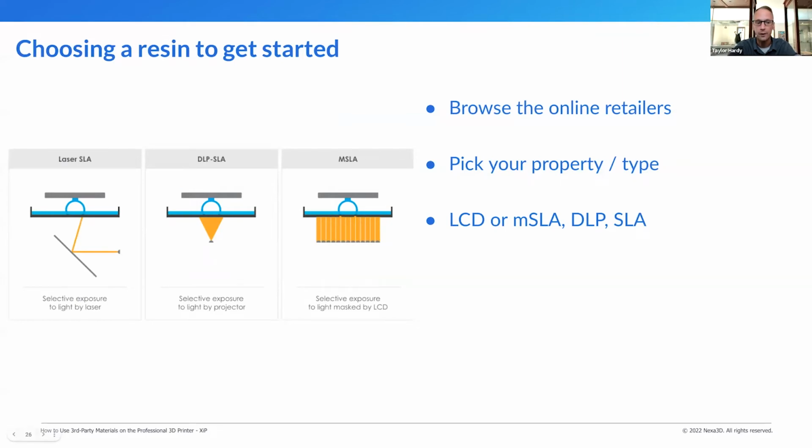So of course you want to make sure you're picking the right type of resin. Some are listed strictly as DLP, some are more for LCD, SLA, some are both. And then of course you also see some that are specifically advertised for MSLA, that's what I prefer to go with, something that is going to 100% work with the machine that I'm using. So of course you always want to be cognizant of what resin you're buying, because there are a lot of options out there.